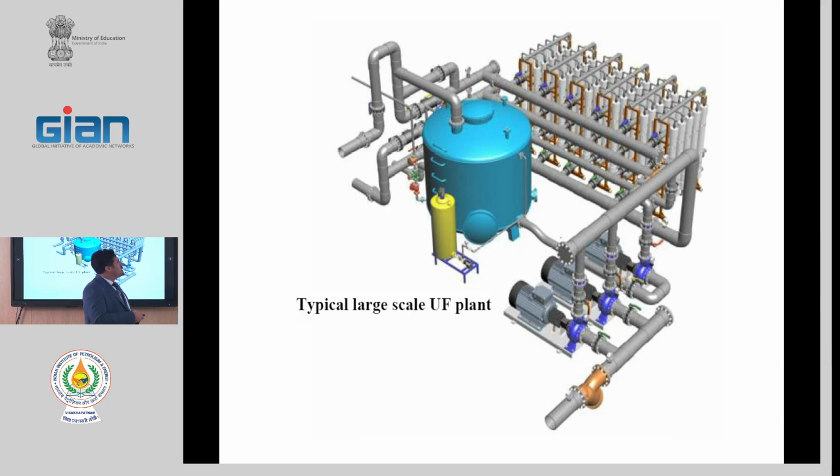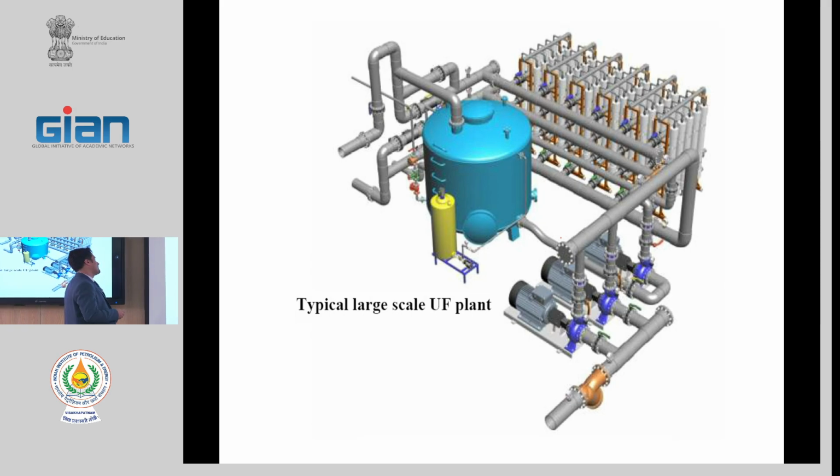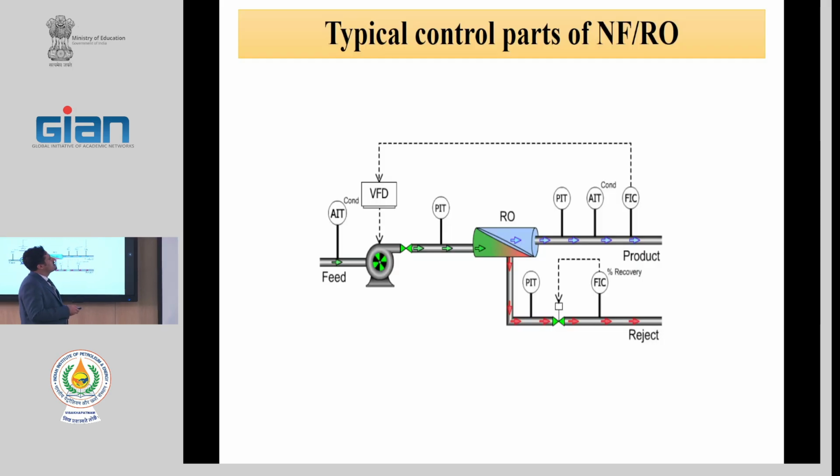Anti-escalant is usually inserted into the RO feed for reducing the sedimentation of saturated salts, and many other additives can be used. Then the feed goes to the modules and divides into streams. This is a usual UF, NF, and MF process.